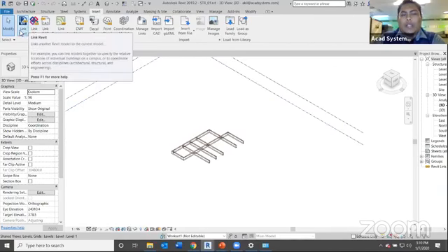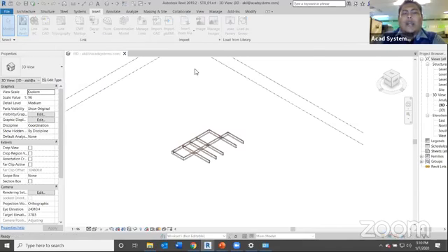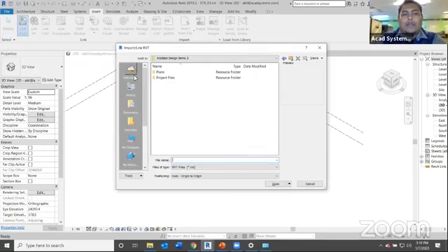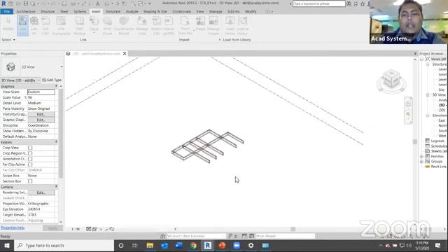The same goes for this cloud platform BIM360. You can still use Link Revit, but the way you find the file is directly from the cloud server. It brings you to the cloud folders. Let's say you want to deal with the latest ARC02 file, link it, and click open.